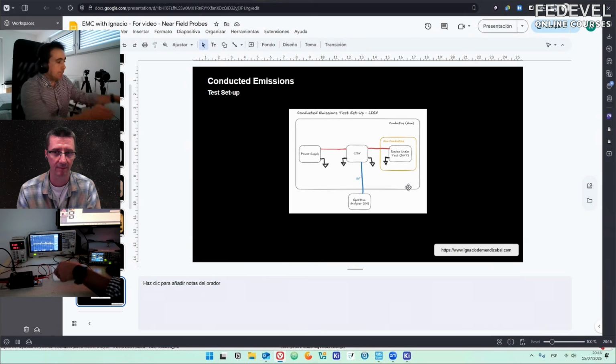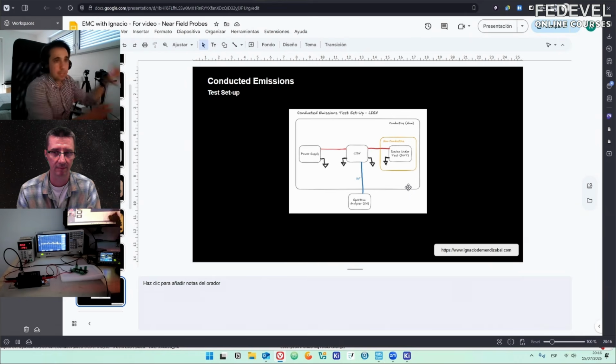And this is to change the capacitance between the setup, between the DUT and the cables, and the ground. And this is a conductive surface. In a compliance environment, this is copper. In real life and in home setups, where you need to move your setup or visit a customer and support somebody, this roll-up aluminum plane works perfectly.